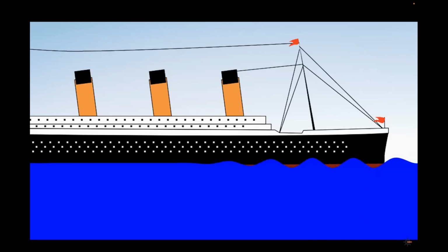Now the problem with this is it increases the drag of the vessel. It's in contact with a larger surface area of water, it's coming higher up the hull, the water is moving at an inconsistent speed because it's going up and down as well as along. This increases the fuel consumption of the vessel. We need to find a way to mitigate this wave.